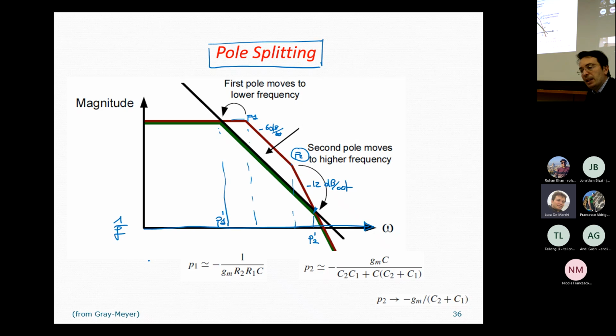So having a smaller zero is a problem, because basically the zero compensates the effect of the first pole, therefore pushes at higher frequencies the omega null value. So here we have the omega null value if f is equal to 1.